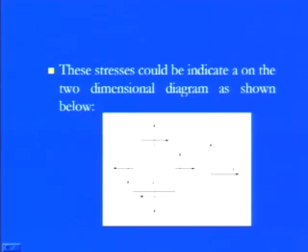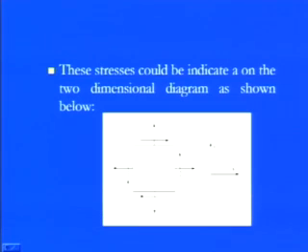And the remaining part you see is tau xy or tau yx. We are considering here that this is the tau xy, which tries to rotate this object in a clockwise direction. So if we want to maintain the equilibrium of this object, then we need the complementary stresses. They are coming from this domain, in this direction and these directions.